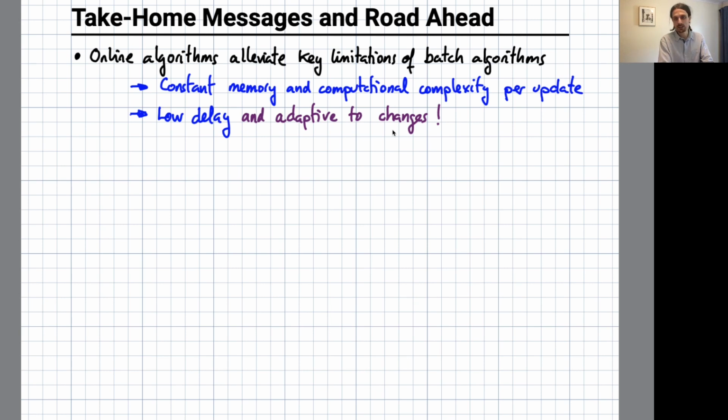And this is actually a very common approach in signal processing when we want to track a parameter that changes reasonably smoothly, right? We just find an online algorithm, assuming that it doesn't change, and then we apply it anyway, even though it changes. So it's a common technique.